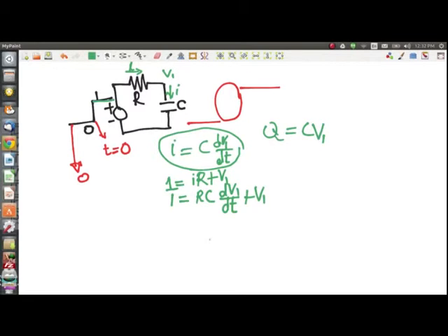But if you think about it, if there is one more capacitor in the circuit, I'm going to have another second order, another derivative, and then to analyze a circuit with so many derivatives is really hard. So we don't actually solve differential equations, well, you can, but beyond the first and second order we don't usually use the differential equation to do it. We use a completely different technique which makes it into a simple algebraic expression, and that's how we solve it.